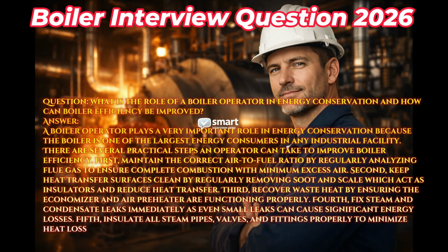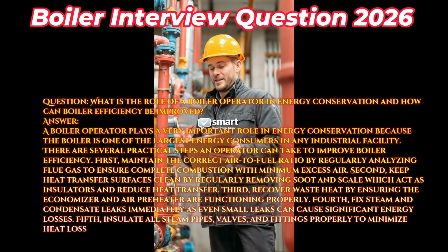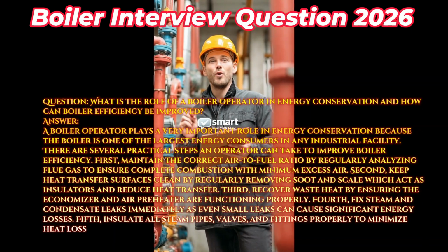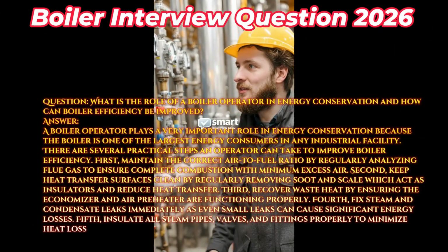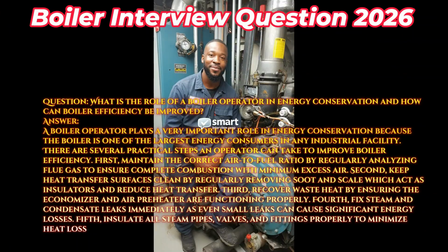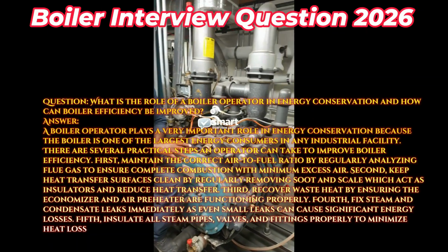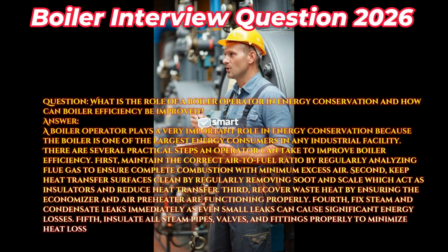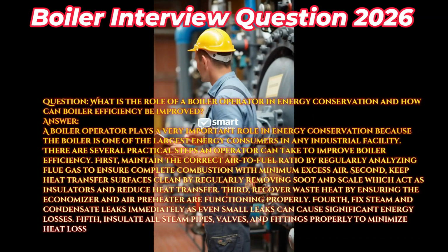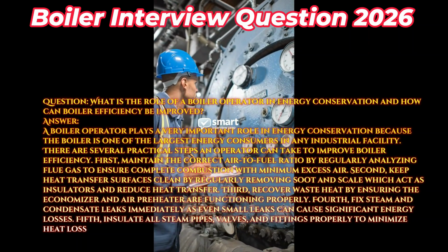Question: what is the role of a boiler operator in energy conservation, and how can boiler efficiency be improved? Answer: a boiler operator plays a very important role in energy conservation because the boiler is one of the largest energy consumers in any industrial facility. There are several practical steps an operator can take to improve boiler efficiency. First, maintain the correct air-to-fuel ratio by regularly analyzing flue gas to ensure complete combustion with minimum excess air.